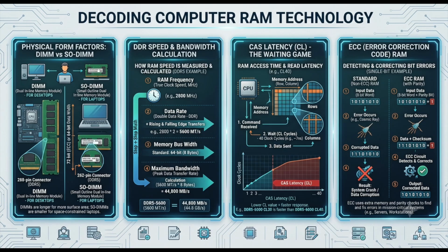When the CPU comes back a millisecond later to retrieve that data, it recalculates the parity. And if a cosmic ray flipped a bit, and that total is suddenly an odd number, the hardware instantly knows the data is corrupted. That is so clever. But standard parity memory only detects the error, right?